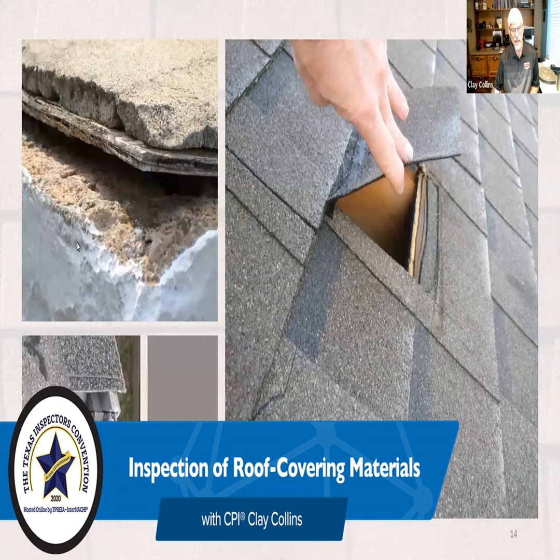It can be caused by the roof cover not being installed quickly or timely. You're supposed to have a dry roof deck, then install a dry underlayment, and then install immediately the roof cover, assuming that the underlayment is still dry.